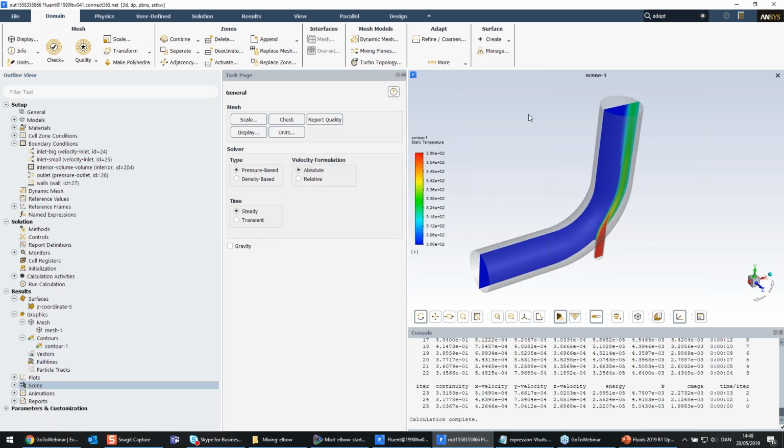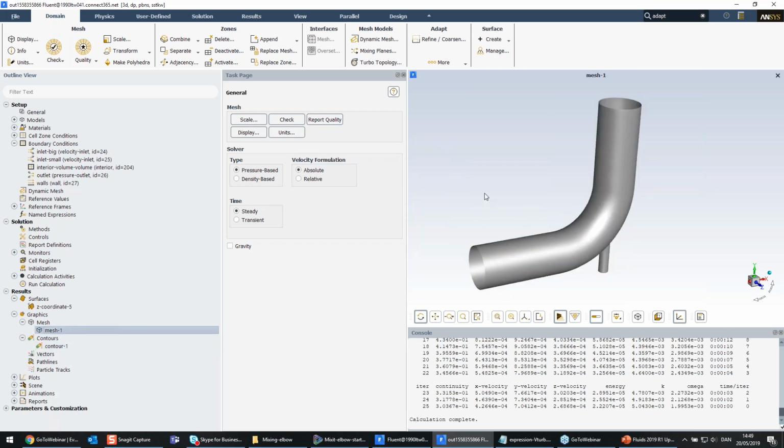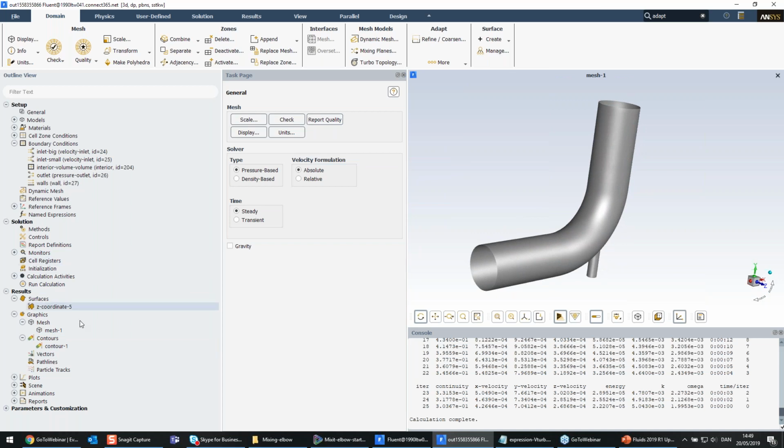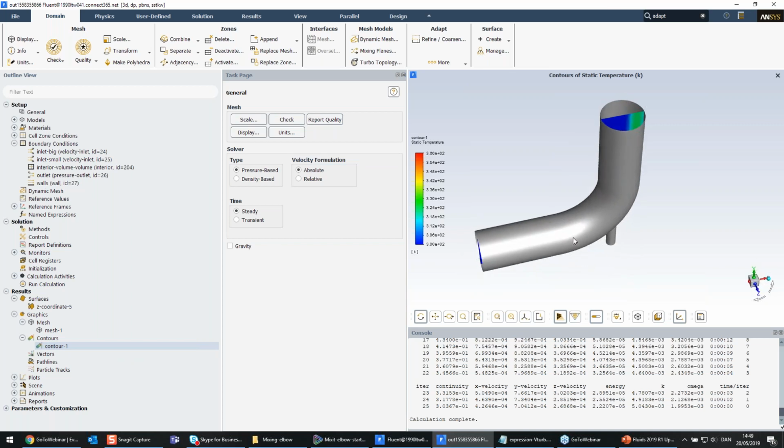And a lot of work has been done on this drag and drop feature. So if I wanted to show just the contour, for example, then I could drag and drop this. So now I'm showing 2. So let's just display this. If I wanted to show the contour with this mesh, then I could just drag and drop, and it would add that to the graphics.